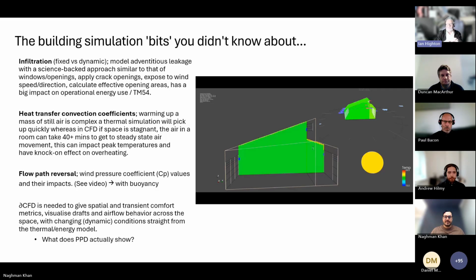I'll start with the third one. If you look at dynamic simulation models, typically you're getting 100% heating or cooling through the day, for example, and then at night it drops off to virtually 5% if you've got parasitic power turned on, but it's virtually zero. Whereas when we looked at the data from One New Change, 100% during the day, and then it dropped to 50% at night. So there's 50% power consumption during the night, which seemed to me colossally high.